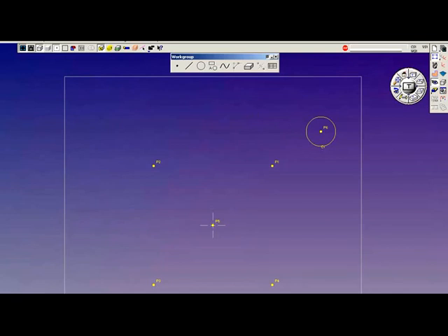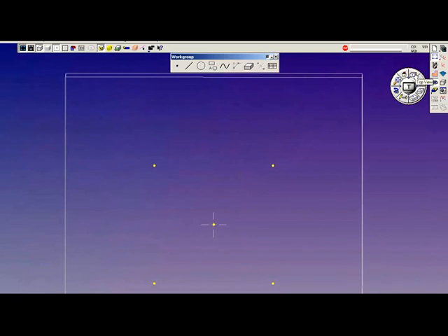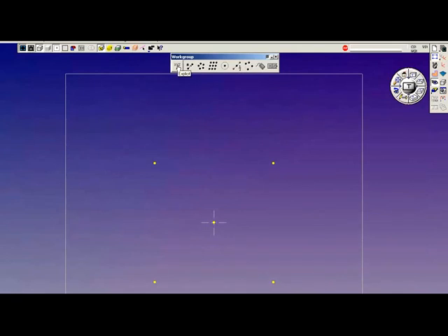Let's delete that point, Control Z, and we'll delete that circle also. Control L turns off labels and allows me to view the points without any labels present. All right, back to the point tile. The next feature is a midpoint, or a point midway along a selected feature. This midpoint works well on circles and lines.